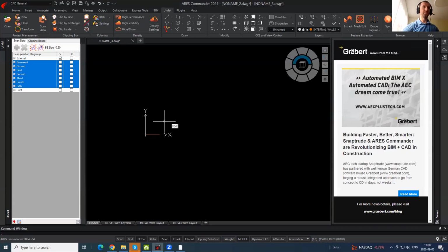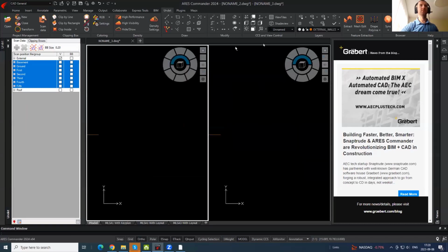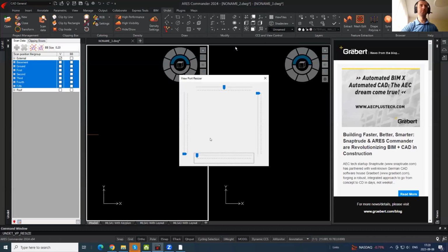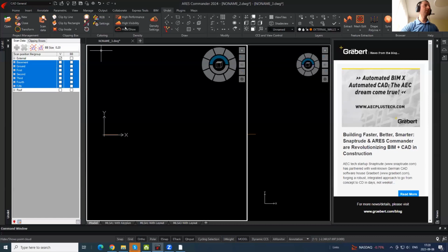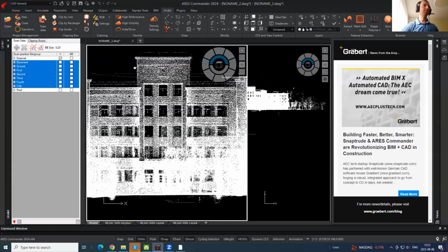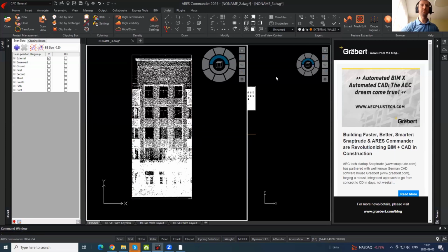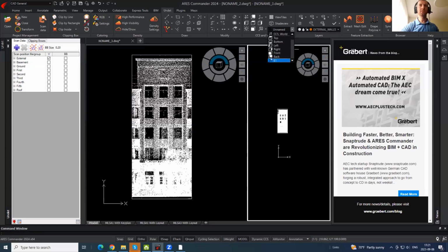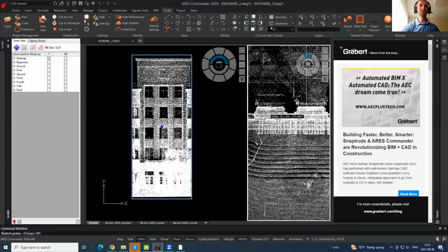Let's switch to 2 viewports. One will be the front view, another the view from the top. Later you will see why I'm doing this. Activate the full point cloud and clip our part. This beautiful part. And here, let's switch to the top to control the depth of our point cloud. Now it's through the whole building. I need only one front plane here.